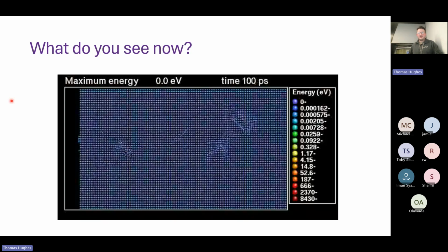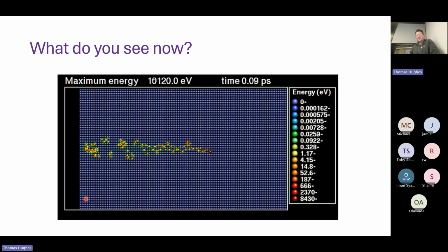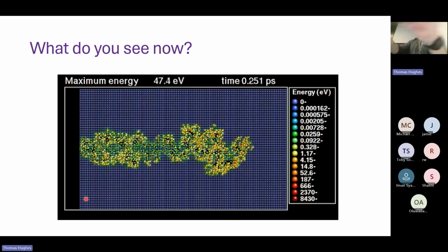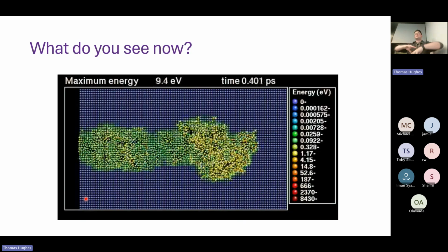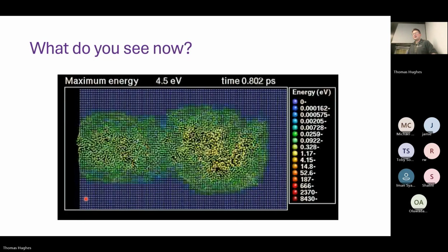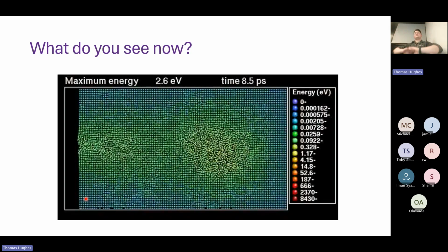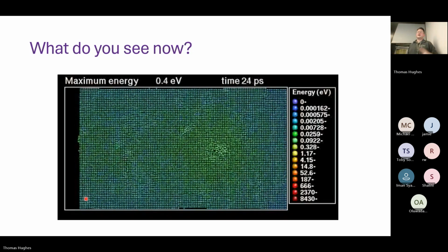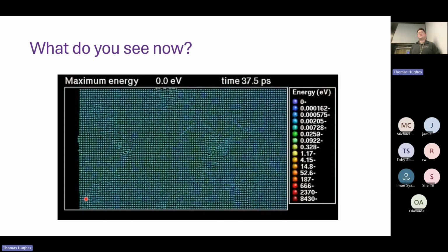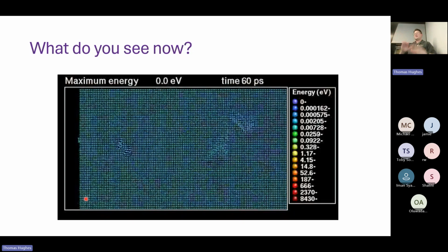If we have a look at this step, if we go again, yeah, very fast. It was a quench, right? We see our collision happening, then lots more collisions, and they spread their energy all around, almost to a gaseous stage in the middle where there are no atoms. Very quickly, that energy has been dissipated. Once there is no energy left for any more collisions, our atoms fall back into place, and we're left with some vacancies and interstitials, which over time will lead to our overall radiation damage and our macroscopic effects.